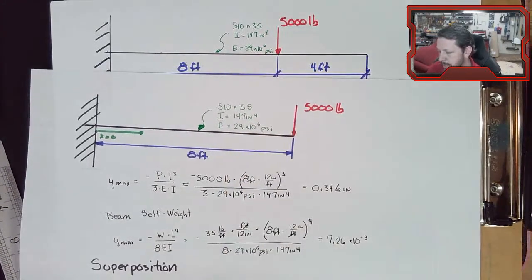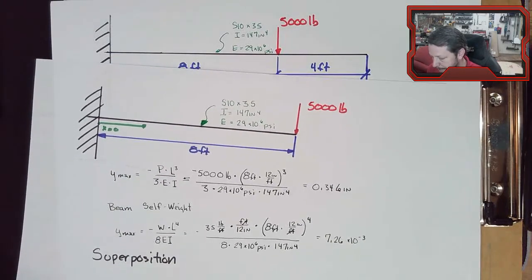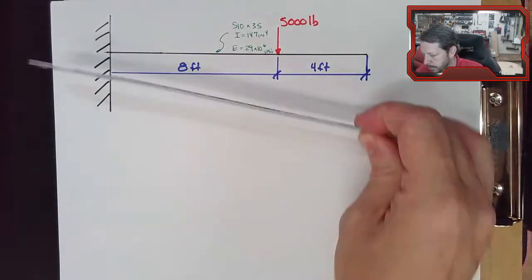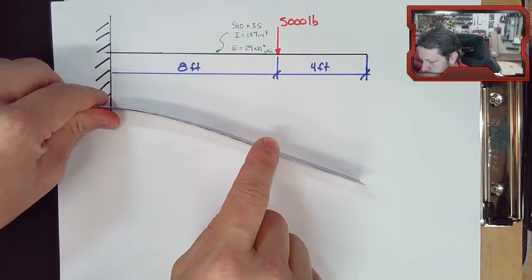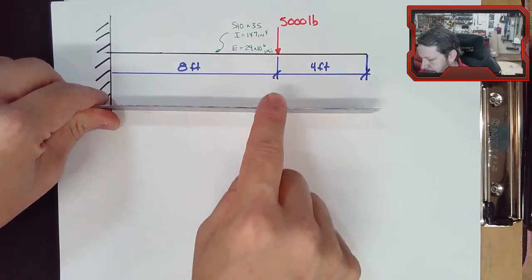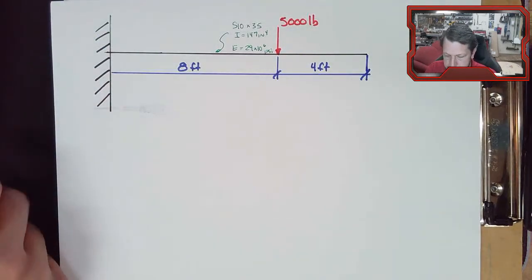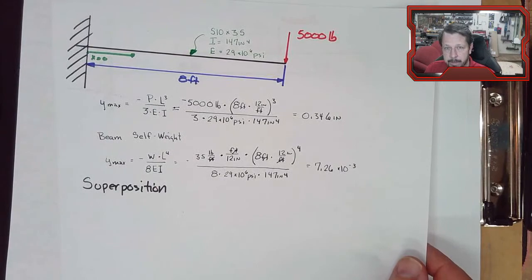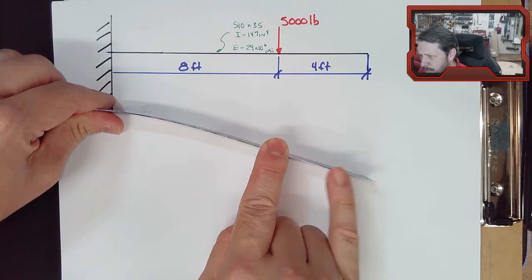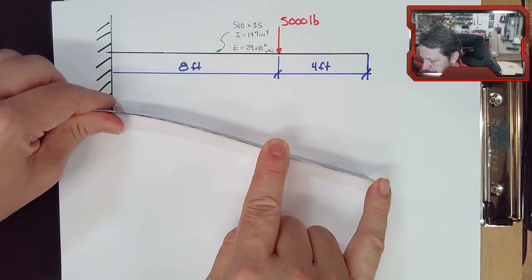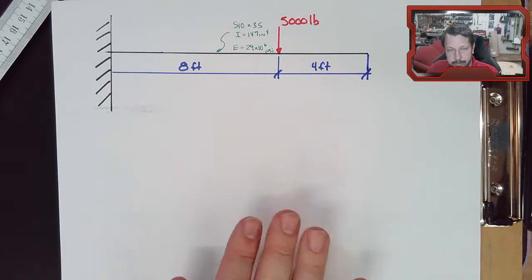So now it's the exact same beam, just longer, 4 feet longer. So what I would expect is that, got the beam, I'm going to cause it to deflect. From here to here, where I'm deflecting at, that is exactly the one we just did. The only difference is that there's more to the beam. There's some more deflection over here. So I just need to figure out how to take that extra bit of deflection into account.